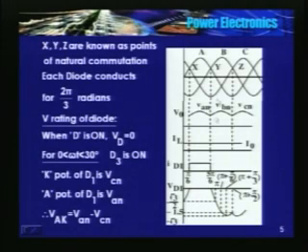I have drawn it here. At this instant, pi plus pi by 2 minus, it is actually minus 1.5 per unit. So remember, drawing this is not very difficult either. What you need to do is find out the instantaneous value of each phase voltage. At this instant for phase A and phase B, you add them up, and you will get it. So the peak value of the voltage appearing across the diode is √3 per unit.